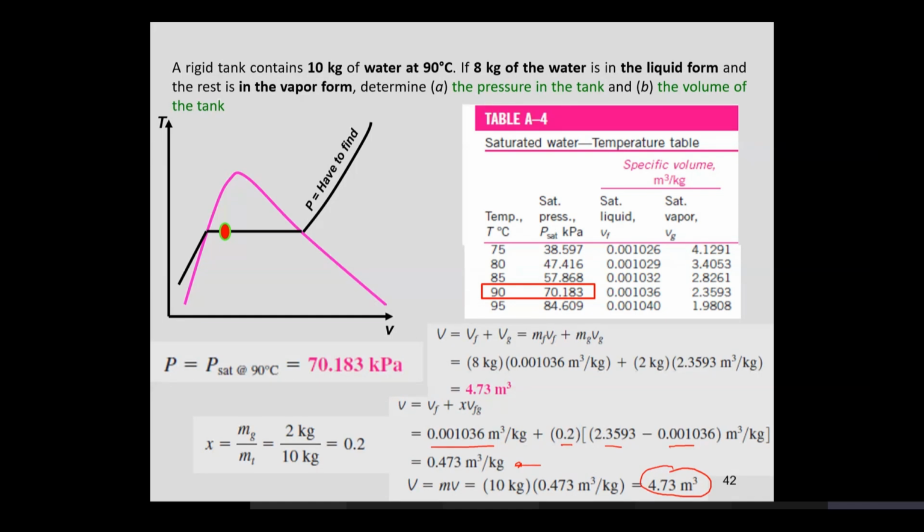Moving on, we have the next example. The next example would highlight two important aspects of the table. Let's first see what the example says. It says determine the temperature of water where the pressure is 0.5 megapascal and enthalpy is 2890 kilojoules per kg. The first thing for you is to identify the table. Any idea how would you identify the table?